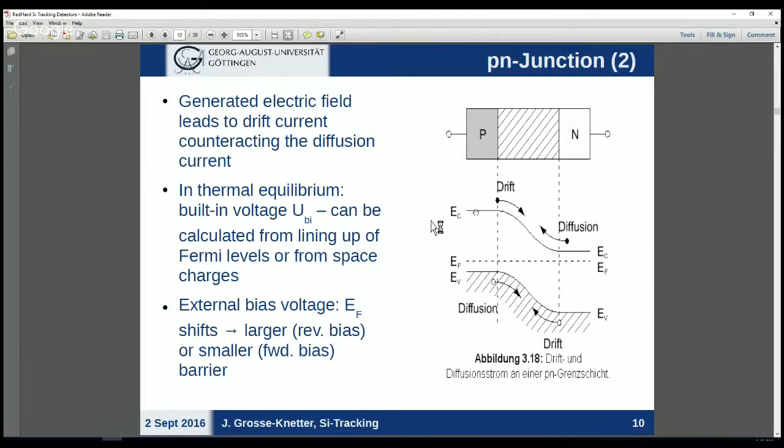So if you want the potential difference between the conducting band in P and in N-type, the result is that it causes a drift which counterbalances the diffusion from the two opposing majority types, and in the end an equilibrium is reached. So we make use of externally disturbing this equilibrium, so we deliberately shift the Fermi levels even further against